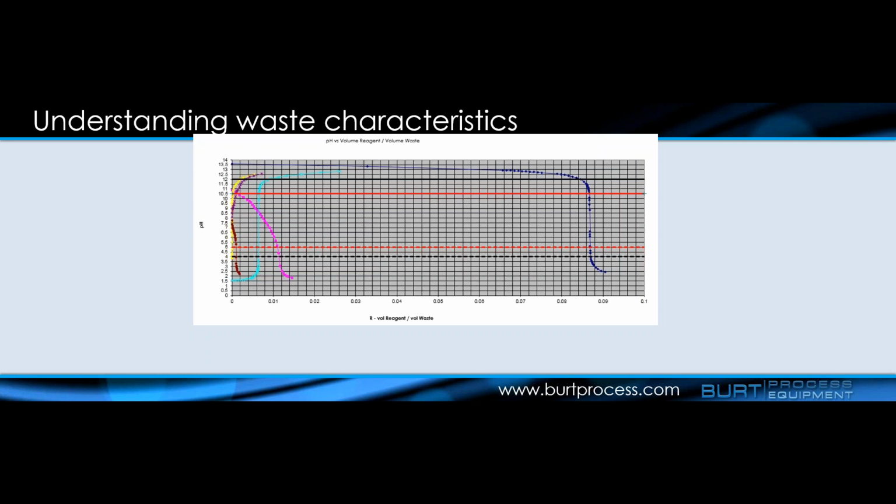We do have a question here, and that does concern the alkalinity. Alkalinity is a bit of a tricky subject because it gets a little bit into the chemistry here. And the question is, does buffering only happen near the midpoint pH or can it happen at a higher or lower one too? So buffering does not only happen at the midpoint pH. But from a pH adjustment standpoint, that's where we want to control the buffering if we have a low alkalinity waste stream.